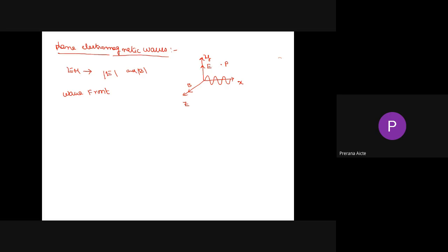Wavefronts are geometric planes, in comparison to a point source of radiation, which sends waves in all directions. If the wave is propagating in all directions, that is an isotropic source, but no antenna can radiate equally in all directions. All practical antennas are directional antennas. No antenna is isotropic. All the directional antennas propagate the waves in particular directions. The surface connecting points of equal phase is a sphere in these situations, that is, in spherical coordinates.